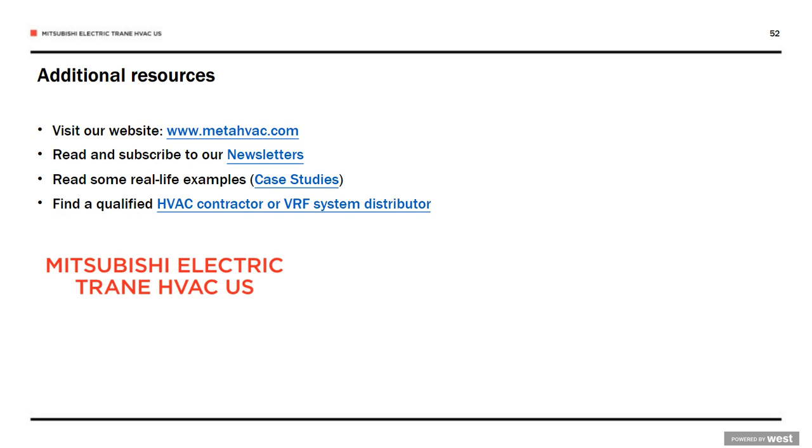So you can use a pump if you'd like, a condensate pump. You can also just use a drain line and have a drain riser. Say that you have a five-story building, you might run a condensate riser from the top to the bottom, and then out some kind of floor drain or whatever. If you can use a gravity drain and avoid using a condensate pump, that's the preferred method, because that's one less device that can have an issue. If you have to use a condensate pump, you have to use a condensate pump.